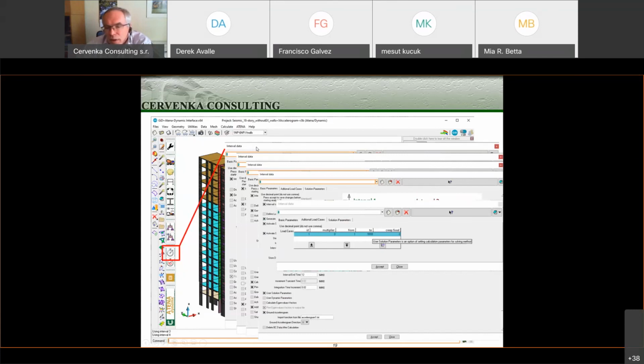For instance, in my case here, in the first interval, I defined boundary conditions and maybe also some fixed contact conditions. And now in all the other intervals, I can just say, okay, use the data from interval 1 with maybe multiplier 0, because I don't want to multiply them by anything. They are just supports, and I can then reuse them. So this is something I want to mention. Some users of ATENA may not be familiar with this, because this is a relatively new feature, and it simplifies greatly the definition.